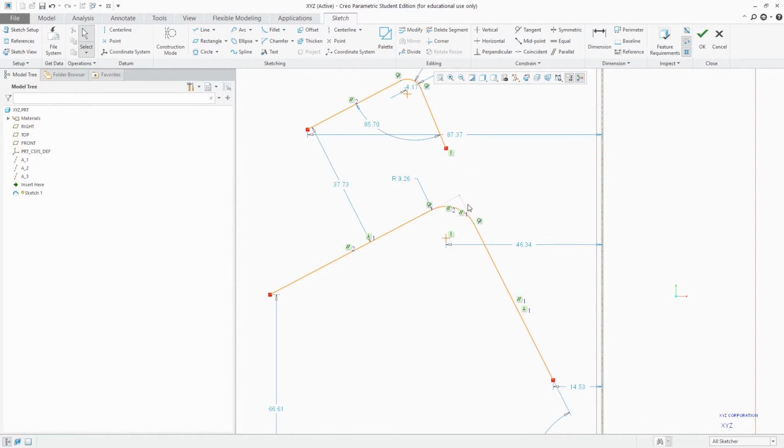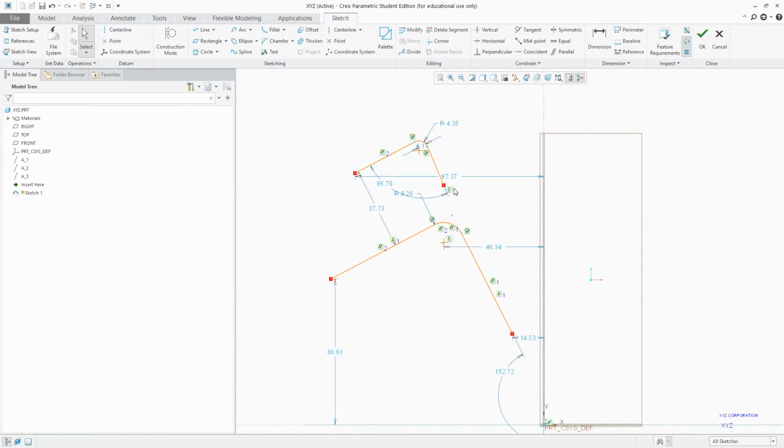So this is the only difference between both, and generally in PTC Creo, most of the time we prefer to give fillet in 3D, not in 2D, because it is quite easy to manipulate if we are giving fillet in 3D. We will see later on, but as of now you can see how we can create a radius, and you can change the value.